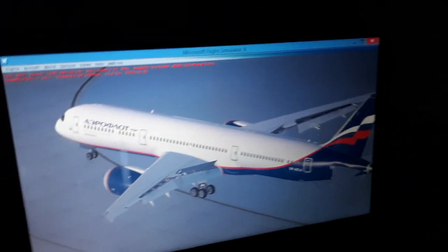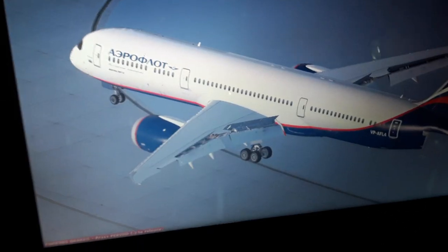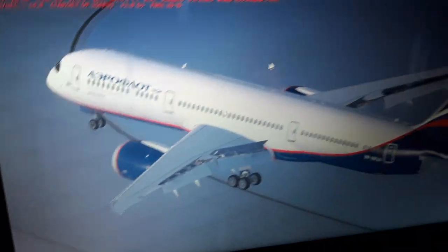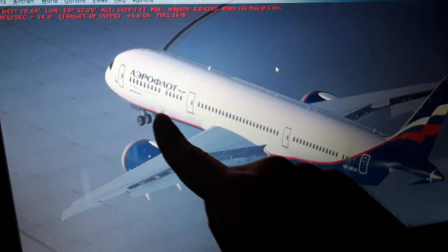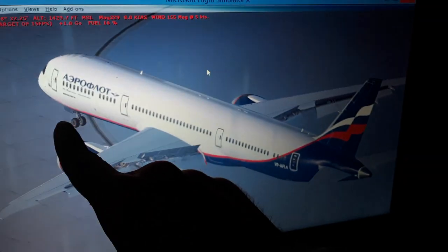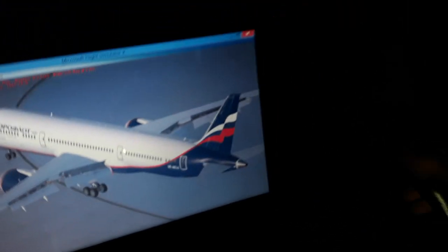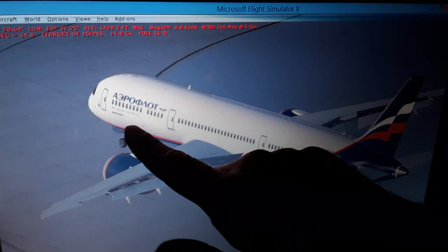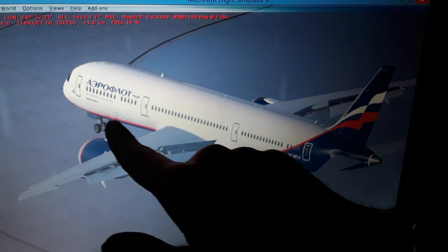Also to yaw the aircraft, we have the forward nose wheels over here. So we can deflect the forward nose wheels 76 degrees to the left and right side, from 0 up to 45 knots or 72 kilometers an hour in takeoff. Then as we increase airspeed above 45 knots, the rudder becomes aerodynamically effective, and then the computer decreases the deflection automatically of the forward nose wheels from 76 to 7.6 degrees left and right.